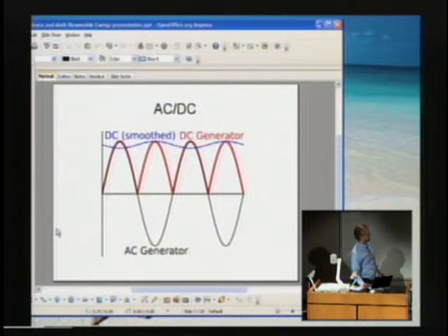A pure sine wave doesn't have any harmonics. If it's 60 hertz, 60 changes per second sine wave, then it wouldn't have much energy at, say, 120 hertz or 240 hertz or odd harmonics. It would look fairly much like this if you looked at it on an oscilloscope.